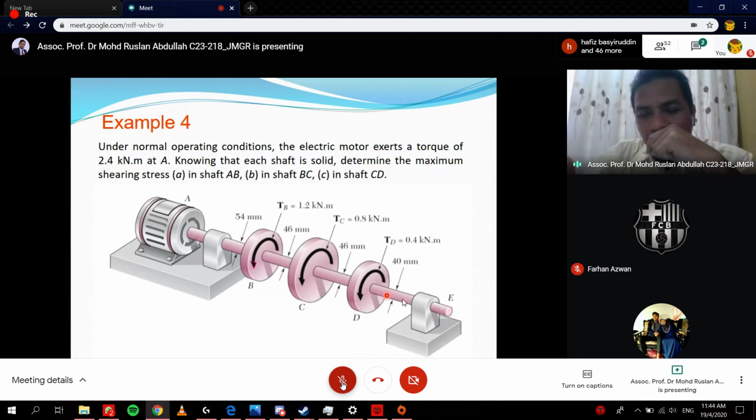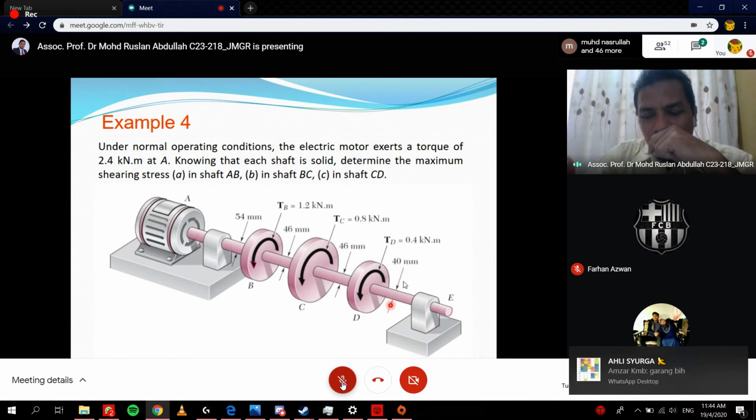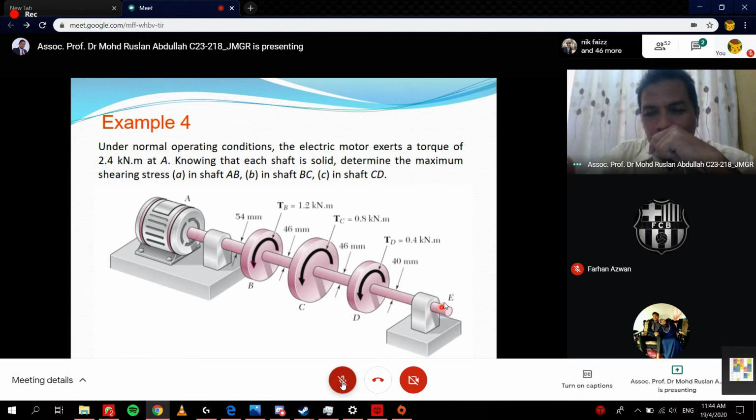The shaft D and E just follows the shaft before that. Here the torque equals 0, except if there is friction at point E. If there were friction at point E, the shaft would develop torque. But we assume that there is no friction here, so the torque equals 0.